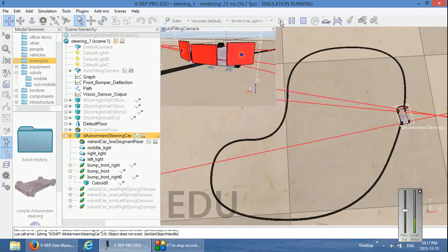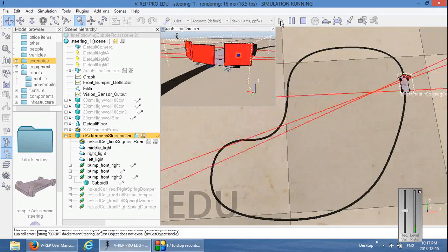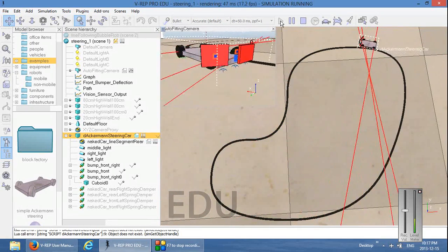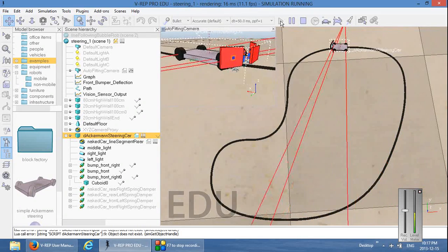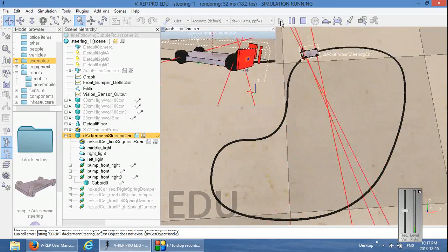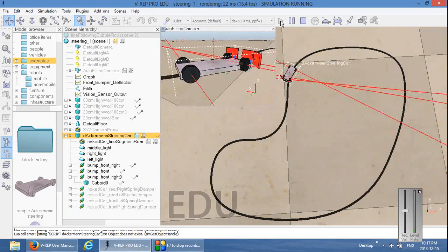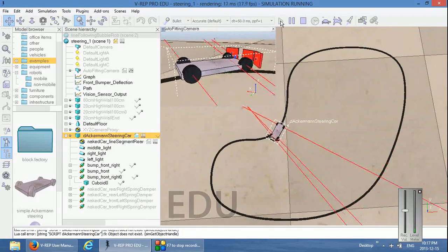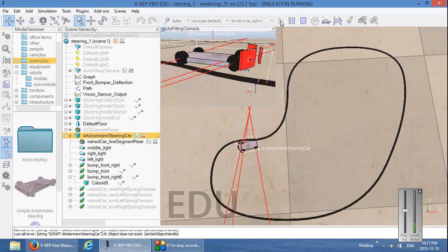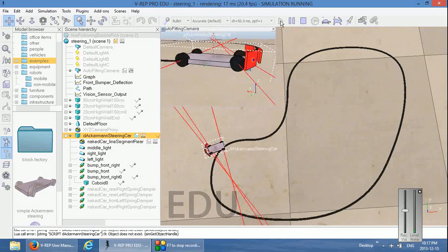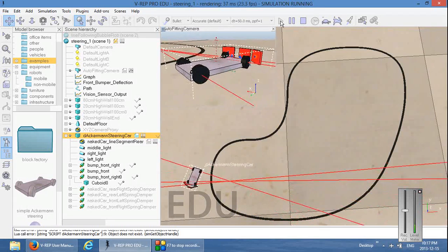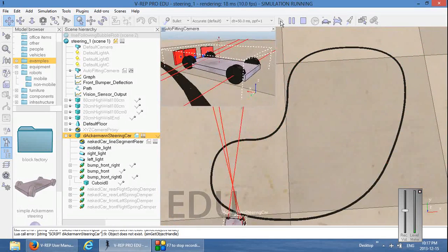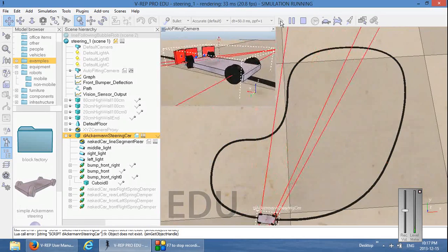And now, just as a bonus, let me show you what an implemented line following robot looks like. Now you can see that to successfully traverse the line, it's a combination of the robot speed and the robot steering angle. You can of course also make it a little bit more fancy by allowing it to either accelerate or slow down in certain areas. And as you can see currently, my steering angle is not big enough for the speed at which the robot is going. However, it seems to be doing alright.